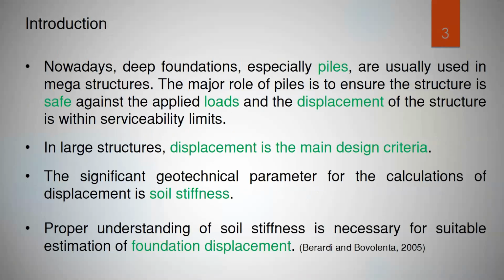Nowadays, special piles are used in megastructures. The major role of piles is to transfer the load from the superstructure to stable subsoil, and the displacement against applied load must be within serviceability limits. The displacement is a stringent design criterion in large structures, and the soil stiffness is the key geotechnical parameter for the calculation of the displacement. So, proper understanding of soil stiffness is necessary for suitable estimation of foundation displacement.